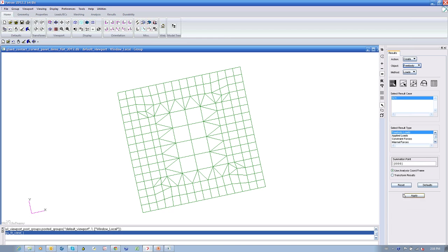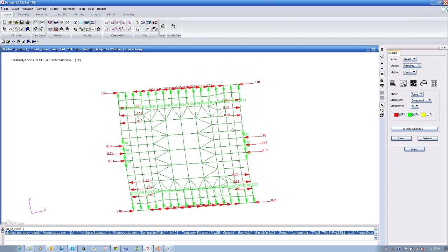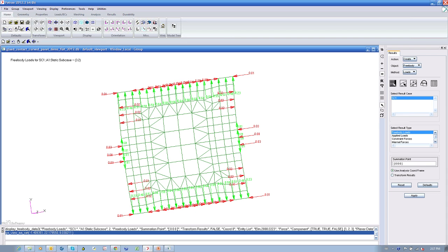and we do the free body plot, and I will turn off the Z, which is a pressure, because we have a pressure, and there's going to be arrows. If not, there's going to be arrows everywhere on that model. So let's put the boundary forces, and we have the load flow at the boundaries. So this is just to illustrate that you can recover and report back all grid point forces at the interfaces of every section that you make of the model. So that's also very, very useful for people that do global local analysis with glue contact.